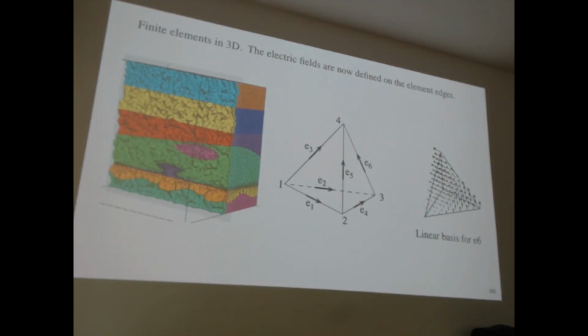And in 3D, the triangles become tetrahedra, and your basis functions start to look really complicated. But there are people who do this, and there are computer codes that handle the tetrahedra. There's a code called TetGen, which is public domain, which allows you to build up these 3D models from the tetrahedra and then work out how to put all your finite element mathematics on top of it.